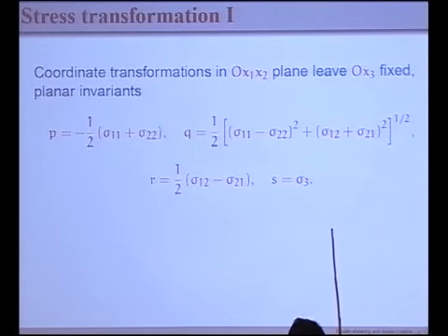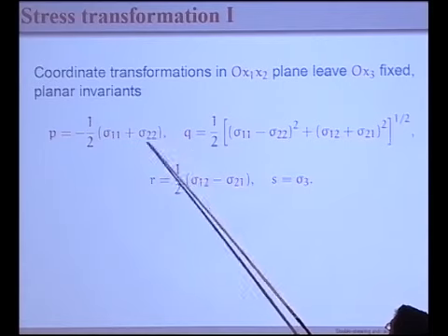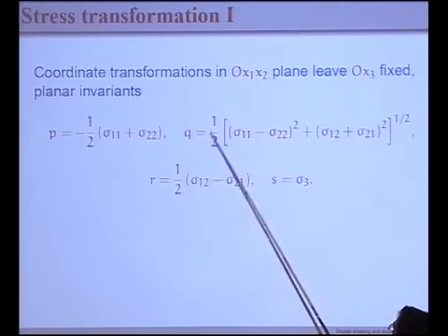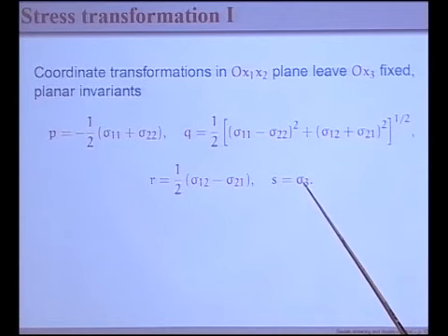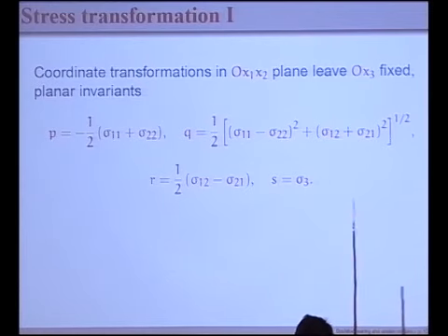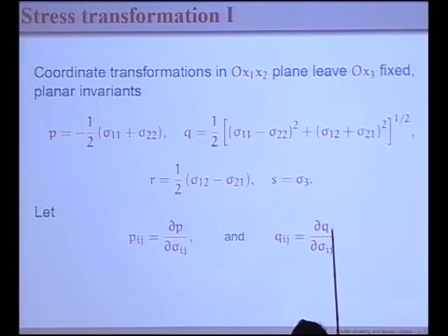And it's very common, particularly in the double shearing model, to move from the stress tensor sigma ij to a set of invariant stress quantities given by P and Q. And if we have a non-symmetric state of stress, then P, Q, and R become the invariants. If I include in the yield condition the intermediate principal stress, or the third principal stress, then for these planar rotations, we have a fourth invariant. So one can use these invariants as a way of characterizing the stress.